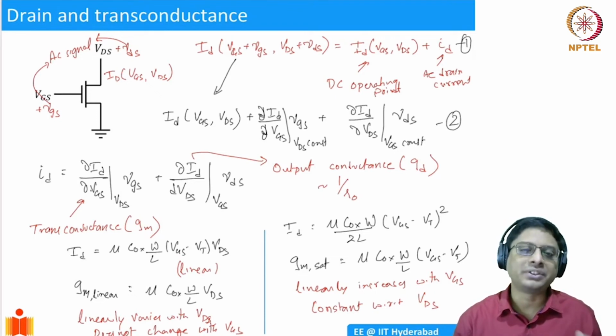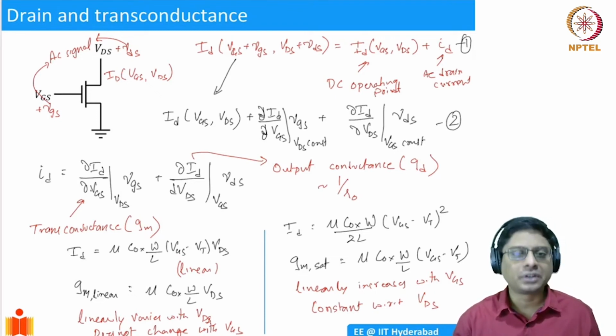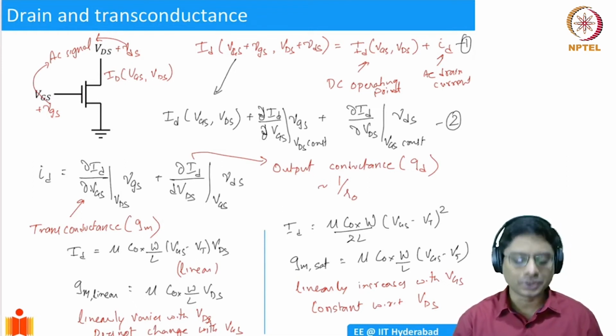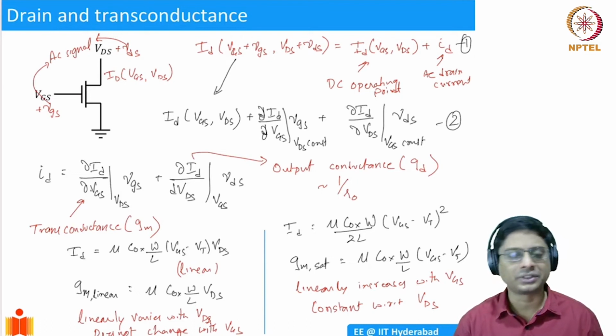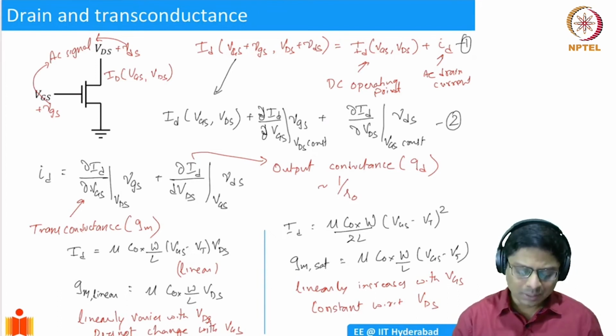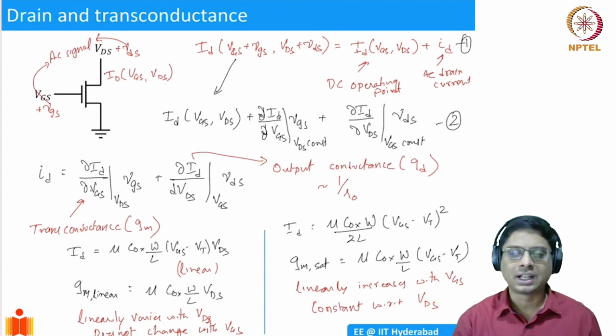But if you look inside an op amp, there will be a minimum of about 9 transistors, or it could go up to 27 transistors or so. You can actually have MOSFET circuits. You design the op amp, like the 741 that you use in your linear integrated circuits course, using design techniques. There are a lot of techniques we can use, things like current mirrors and so on. That's a completely different specialized course that will follow this if you're interested. But that is in the domain of analog IC design.